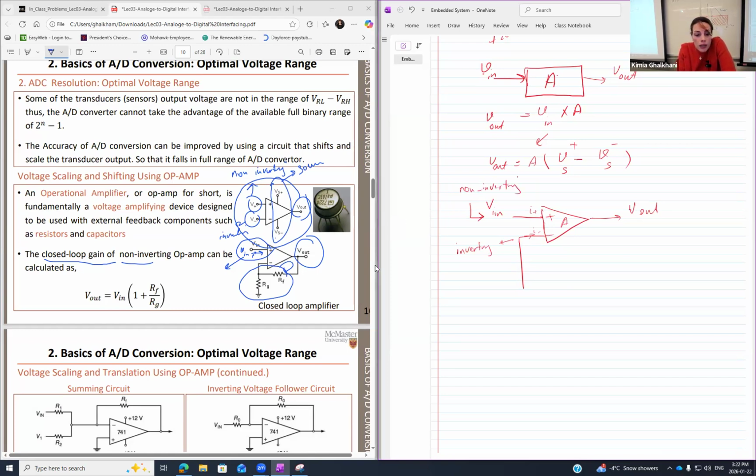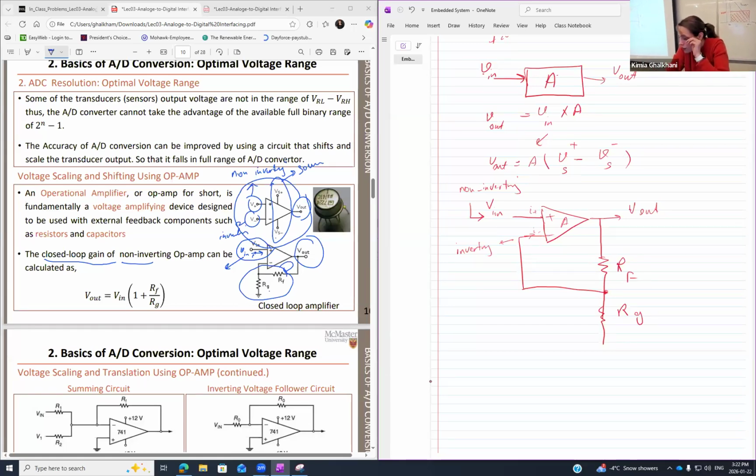And then if I'm going to draw the equivalent of this circuit to make it easy for you to understand, this is Vref, RF. I put it down in here. This is RF. And then this one has a series connection with the other one. And then these two are going to be connected in here. This is going to be my RG, right? G stands for ground resistor. F is your reference. So this means ground resistor, and therefore I'm going to ground here. So this is what a non-inverting op-amp is, and the gain you can calculate like this.